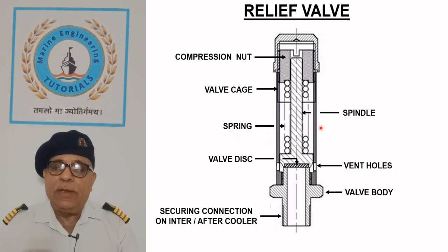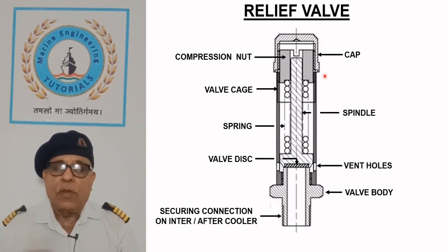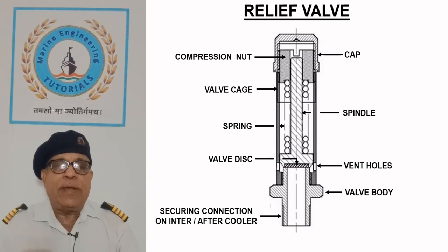A heavy spring keeps the valve closed whose tension is set by the compression nut. A cap is secured on the valve cage and sealed to prevent unauthorized change of relief valve setting.